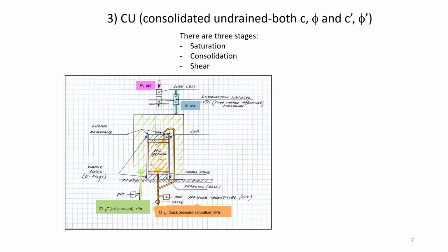What you're dealing with during the tests is cell pressure, back pressure, force, and deformation. The rest of the stuff is just pure calculation.